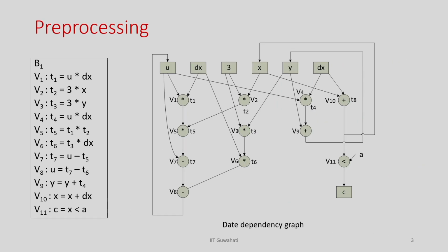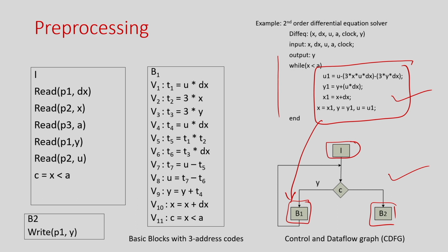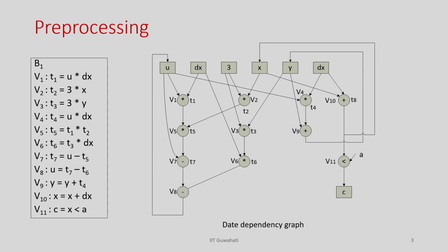So, this is the plan. We have seen that if you consider this particular basic block, the operations here are written in the 3 address form, right. That means we split the operation into smaller unit operations, because otherwise the delay to execute a single operation will be more, and that is not feasible. So we do that, and then from this we identify the data dependency. This is what is called a DAG, a directed acyclic graph, where we represent the data dependency.